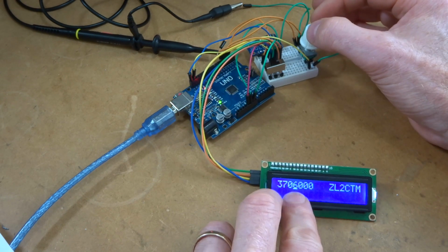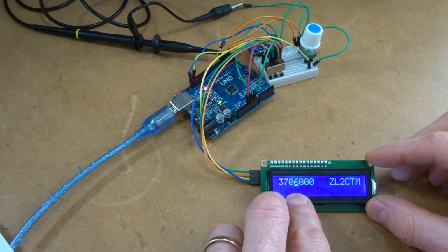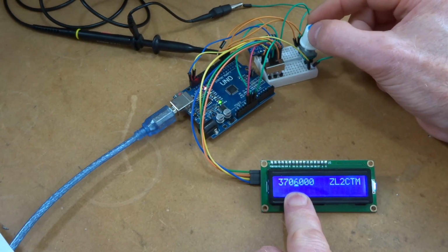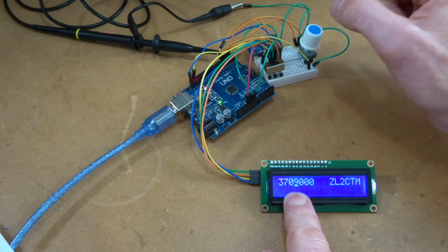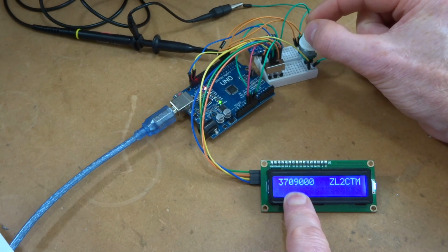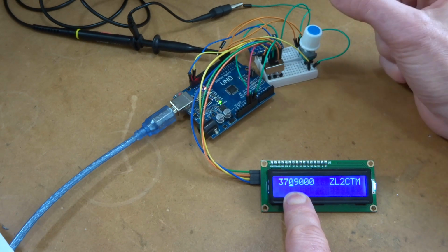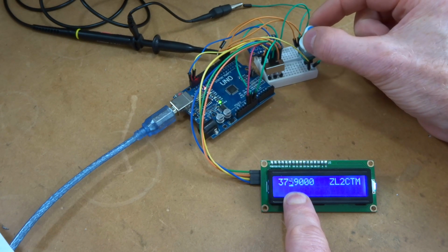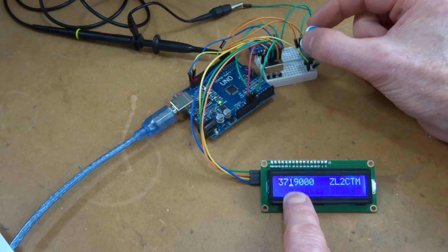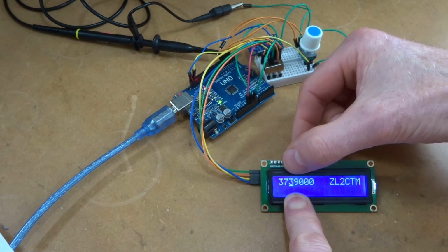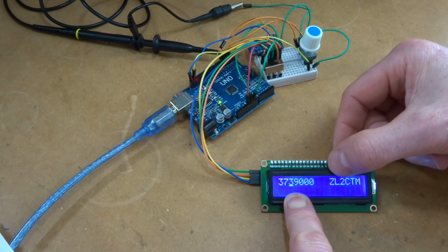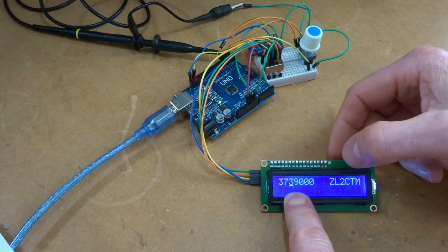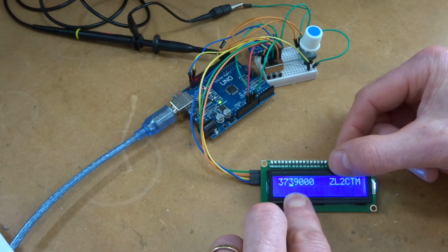You can see there's an underscore there. That's what I typically use for this type of display to indicate which digit is being changed. If I push down the rotary encoder switch, hold it down and then rotate it, you'll see that cursor move left and right. When I release the switch and turn again, that digit has now been changed. I quite like that way of displaying it, as opposed to having over here, say, 100 kilohertz or 1 megahertz or 1 hertz or whatever, what I have called in the software the radix, at the moment.